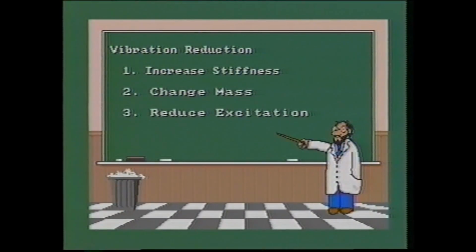Reducing excitation forces coming from steel rolls involves balancing to about 0.02 of an inch total indicated runout at top speed. Additionally, alignment of all rolls to about 0.005 of an inch will not only reduce axial forces, but improve the overall operation. Occasionally, certain problems lend themselves to damping if relative motions of a member are primarily in one direction and are large in magnitude.